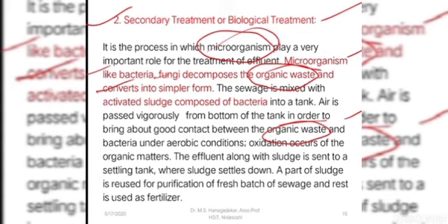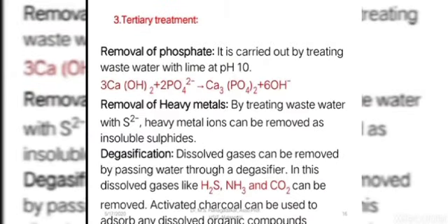as a result of oxidation. The effluent or the wastewater and sludge are sent to the respective storage tanks, where the sludge gets settled down and part of the sludge is reused for the next step, and then a fresh batch of sewage water follows the secondary treatment process. And here the sewage and the treatment are used to remove the fertilizers or organic components present in the wastewater.